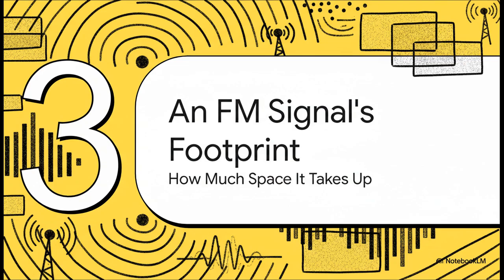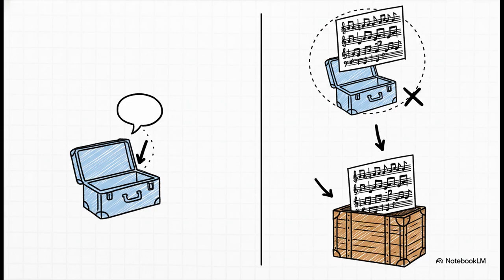Right. So all this frequency wiggling doesn't just happen for free. It takes up real estate on the radio spectrum. Every signal has a kind of footprint, and we call that its bandwidth. And this is really the key takeaway here. The more information you're trying to cram in, the higher that modulation index, the more space you're going to need on the airwaves.